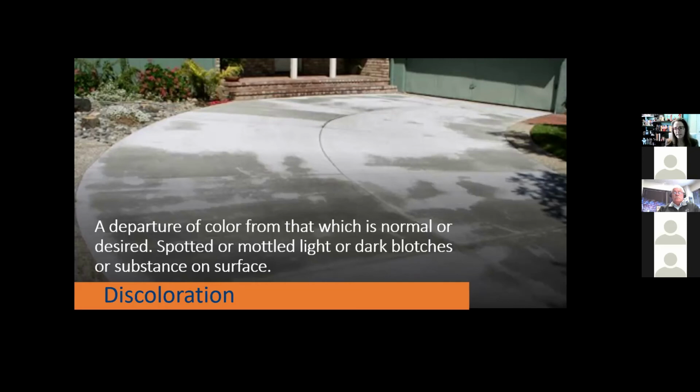So the next time I went back, because I lived in Illinois, next time I went back to the stadium was about 3 months later for games. So this would have been early spring versus midsummer. And because of heat and because of oxidation, it was gone. So it's not always something that lasts. It depends on the structure itself and why it occurred. But it is something that discoloration can be a problem in concrete. Of course, we want the color of concrete that we asked for, but sometimes it's something that's temporary.